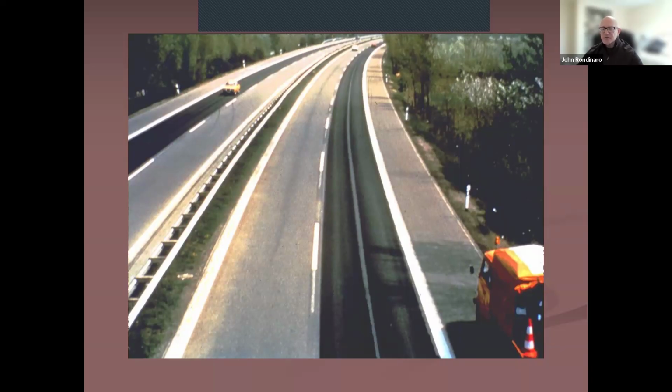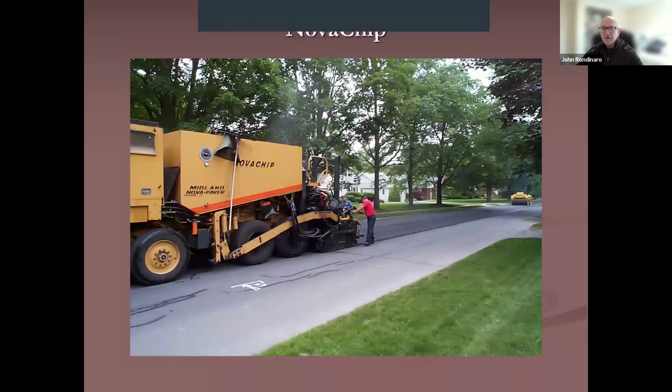You can channel the microsurfacing material into the rut, and as you can see in this picture, you can put down a couple courses. You can put down a couple sections of that rut fill treatment. You see that on the right hand side of the slide, and then on the left hand side of the slide, that's the finished product where you put a final course of your microsurfacing.